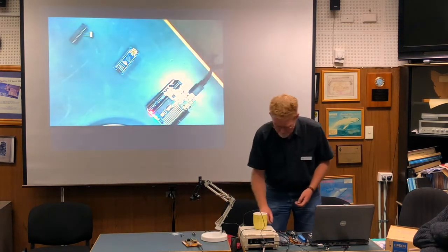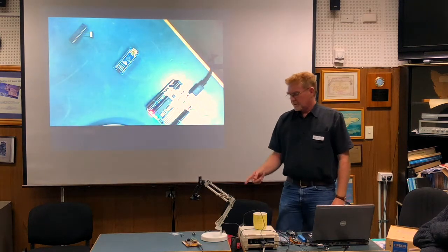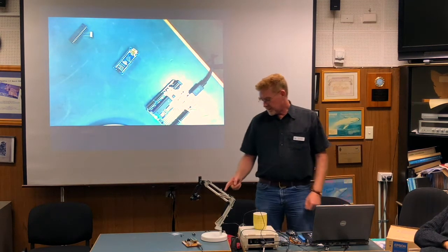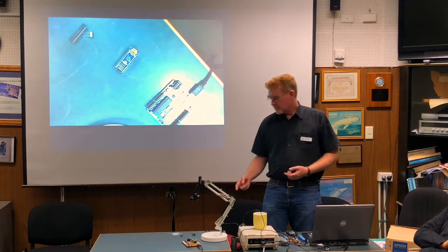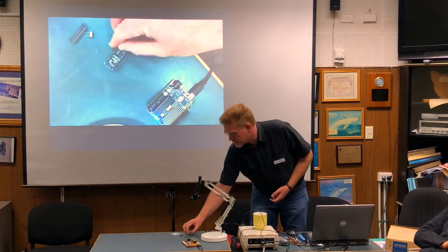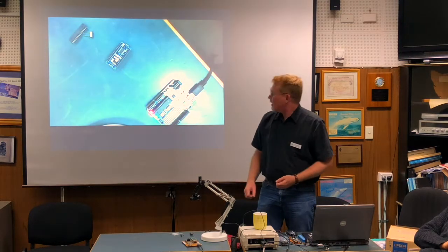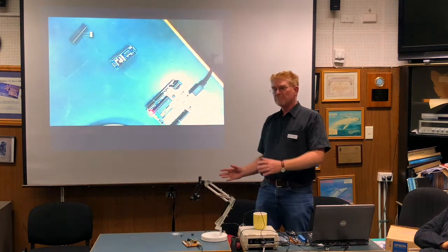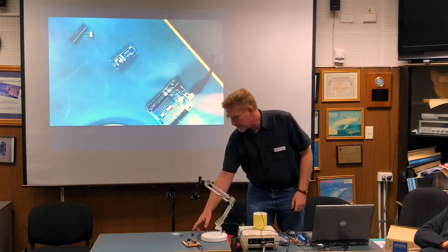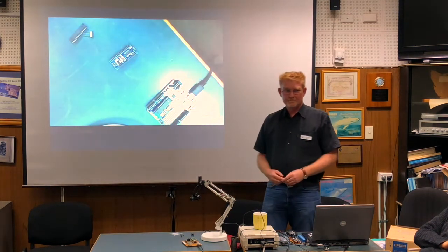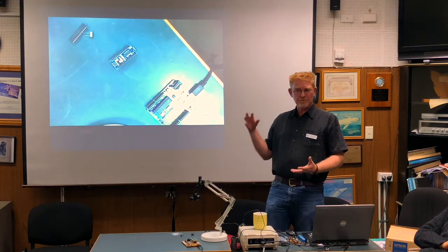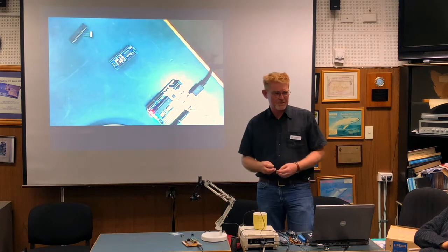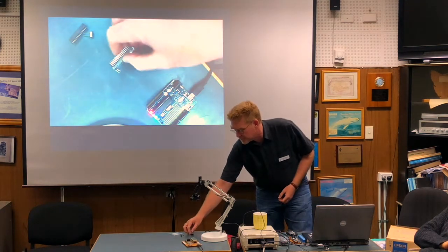This one I've shown you before. One of the tricks around the cheap ones is that the small package means they can make them below a price point, but you notice that the actual headers go down the long sides. I have seen some other small ones people are putting out where they decide to make them even cheaper by making the board smaller and putting pins along that edge there. It's great if you want a cheap one. If you're going to put it into a breadboard, you're going to have some problems because that bit just gets in the way and you lose bits. This is a nice form factor, I've found.